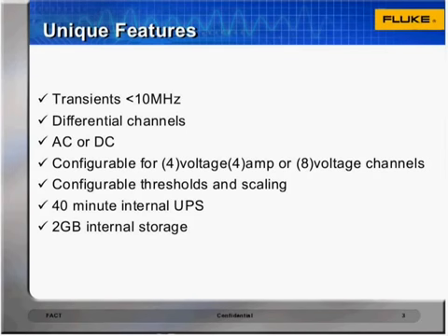To further enhance the flexibility and control of the instrument, a very detailed level of thresholds and scaling can be set to assure the capture of exactly what you want and how. Examples include capturing events based on previous cycle comparison, phase angle change, peak value, or deviation from expected value. When a trigger is crossed, you can set what type of data to record and also at what sampling rate.